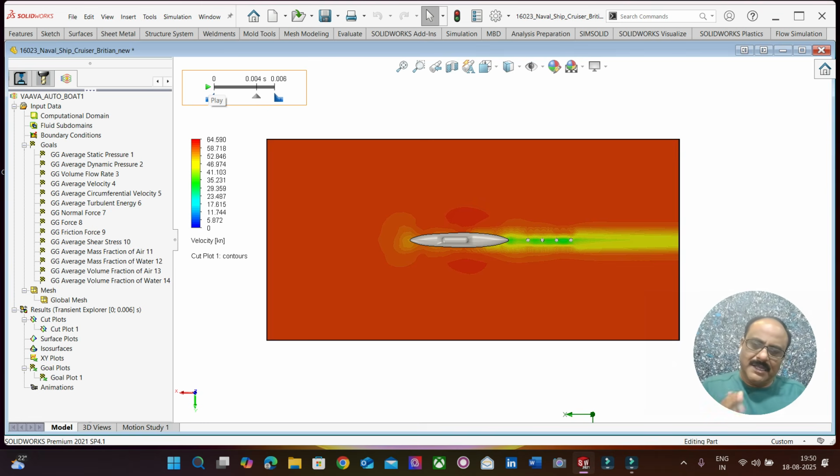It also depends on the viscosity and the other parameters, because for turbulent energy or for turbulence, we need to define the viscosity. Turbulence is a parameter that is defined based on viscosity. So the viscosity of water, the viscosity of air, and what kind of turbulent energy is generated. That will be at time t equal to 0, how much it is, at t equal to 0.1 seconds, 0.2 seconds. Like that, there are going to be about 1,500 to 2,000 iterations, maybe 3,000 iterations. It might take about 6 or 7 hours for such a computation.